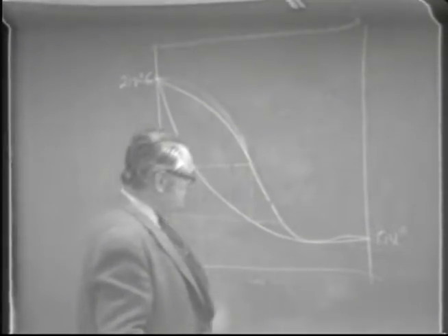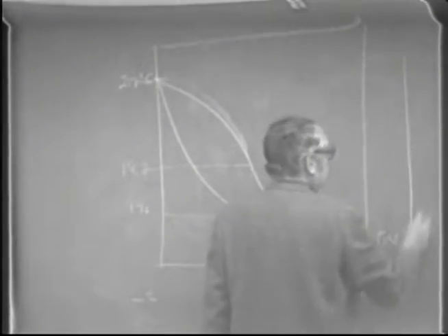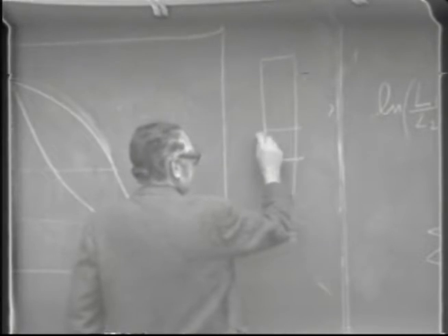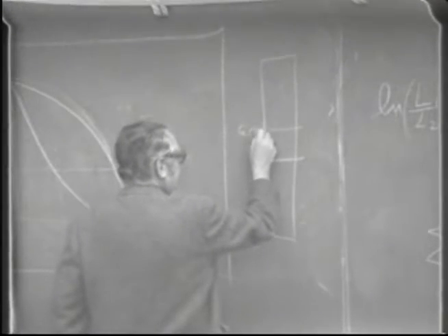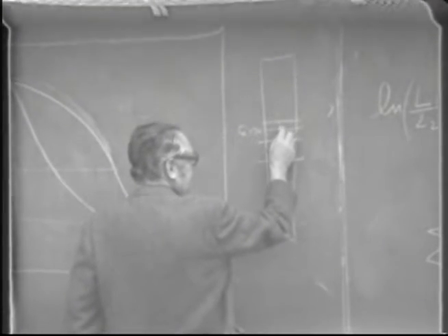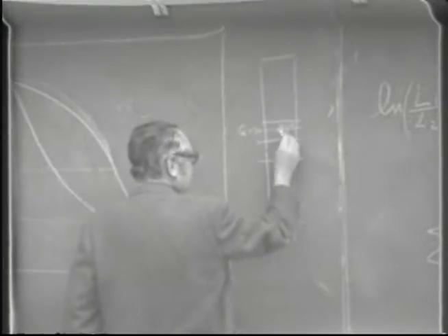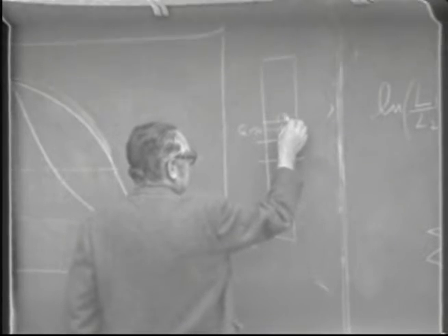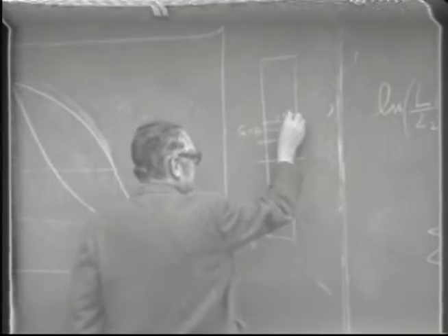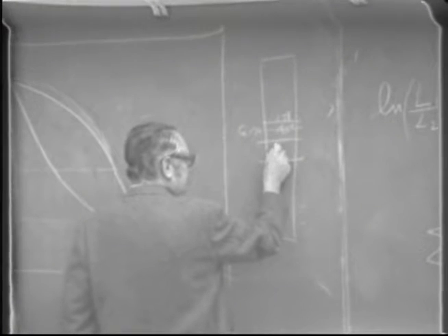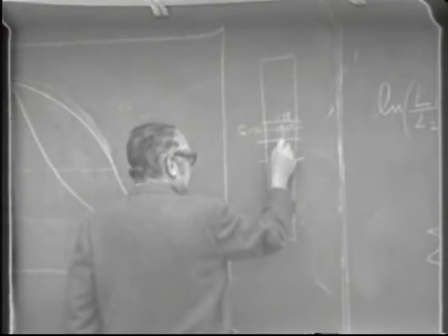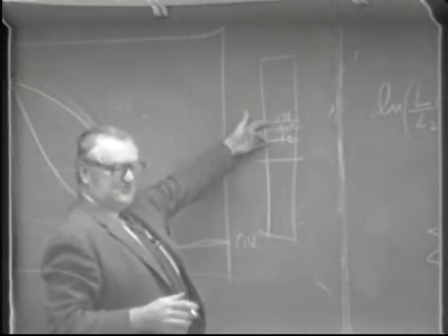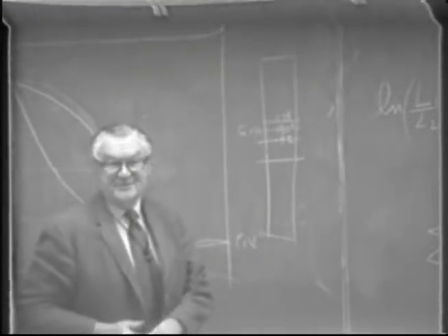And so in this region of a column where the fusel oil decanter is going to be, let's say where you're trying to get about 130 proof, this might be 185 here, and the tray above might be only 177 or 78, something like that, and the tray below might read 195 or 192, something like that. I'm just guessing, but these are reasonable figures about what they'd be.